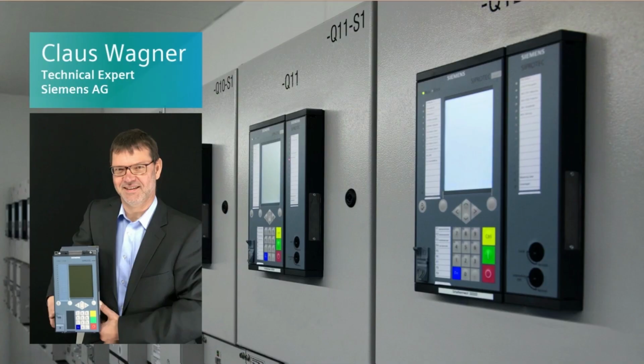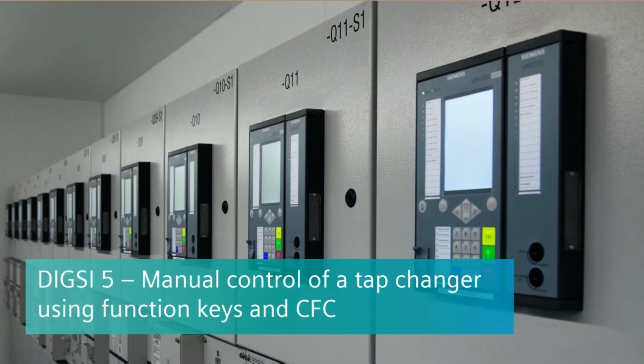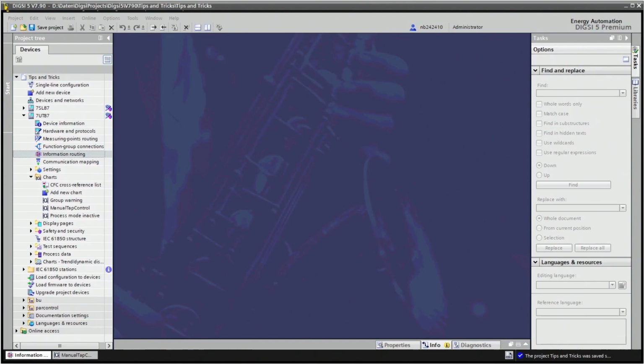In this video I would like to show you how to program the manual control of the tap changer. To control a primary tap changer with SIPROTEC 5, a function group voltage control is required, which we see, for example, when we open the information routing matrix.